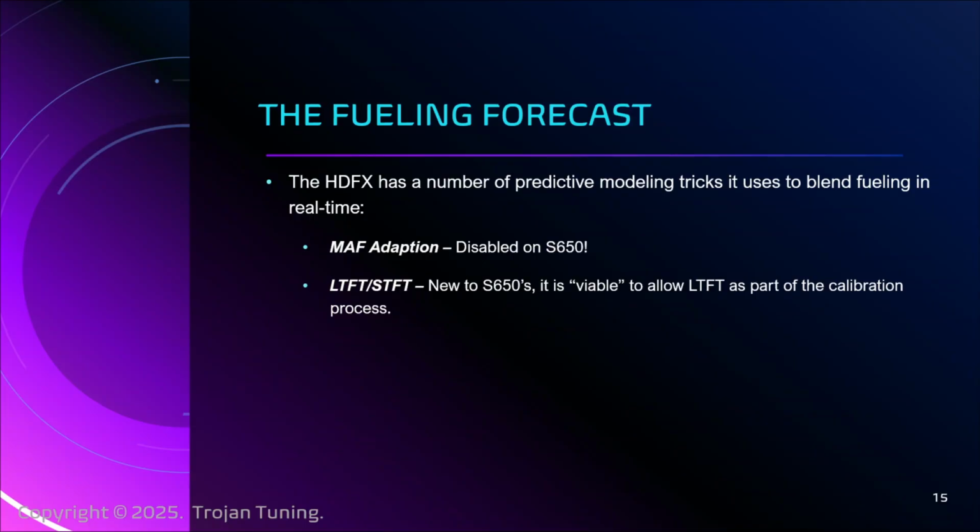Okay, LTFT and STFT. We talked about these in logging and how they're used and how it is eventually used to compute the error and fueling. You can see the previous slide set on that. The thing that's interesting about this, again, is the fact that the S650 ECU is so darn quick. The predictive modeling of the LTFT is, from one cycle to the next, shorter, in that the LTFTs flicker, which is a good word for it, more than they did in previous generations. They're quicker, right? Short term, still short term, right?